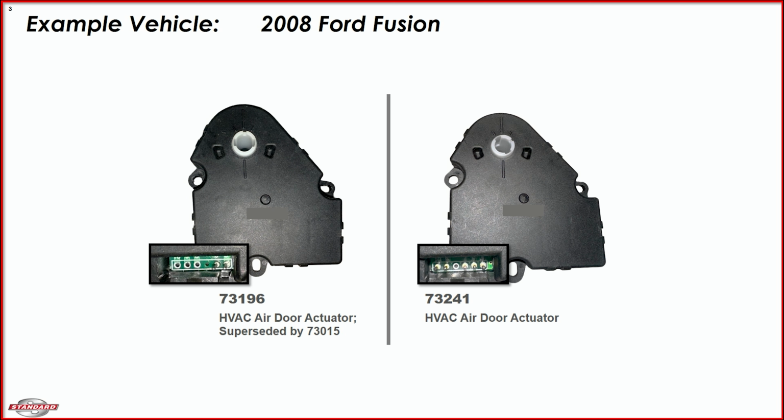What is the potential issue when working with these? From the outside, they look completely identical, but on the inside, they serve 2 completely different functions within the system. These parts are not interchangeable and will produce trouble codes if incorrectly installed.